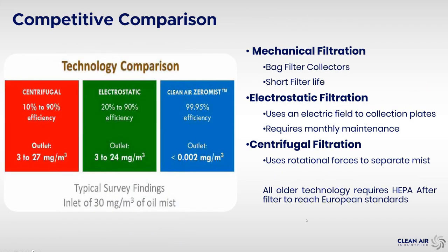But so I mentioned some of the competition out there, and the mechanical, electrostatic, and centrifugal filtration systems, they've literally been around since the 70s. And the mechanical is just like a bag filter collector, very, very short filter life. Most guys forget about it, and then all of a sudden they see a bunch of smoke in the plant, and the reason is because the filter is completely clogged within a month or two.